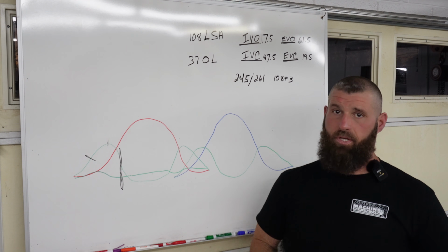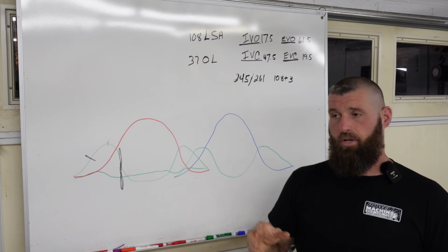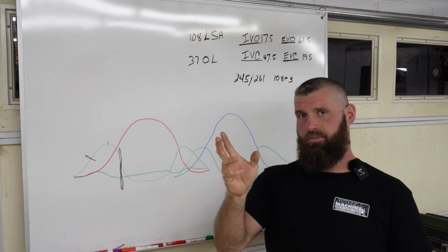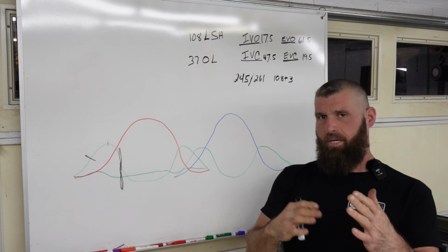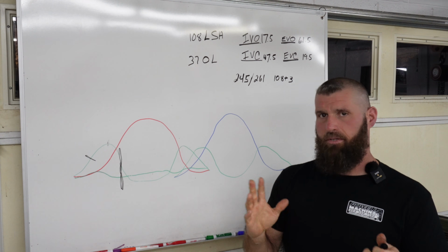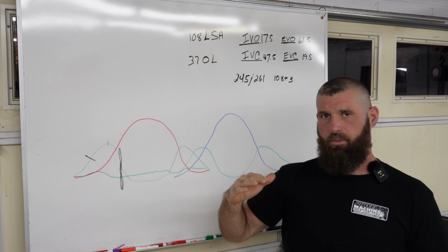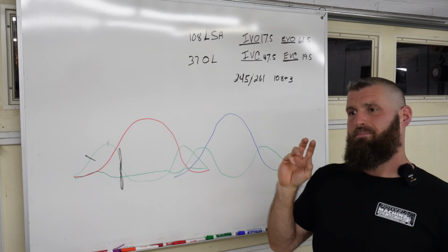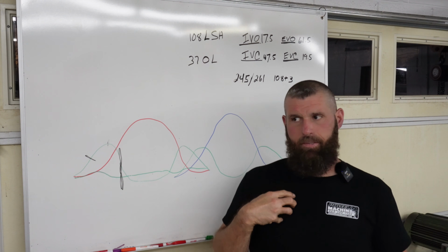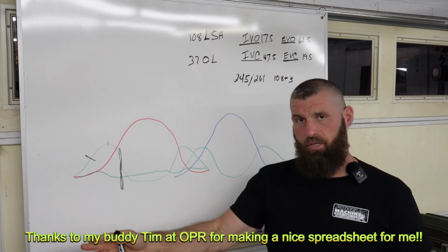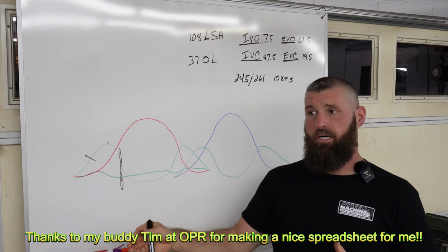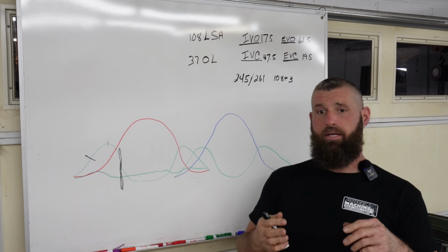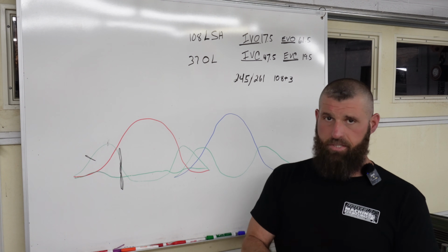So how do you figure out everything else? We looked at the exhaust flow, and there is some validation to 80% and 70% and all that. We got a little sliding scale spreadsheet that says if the percentage is here, then we'll put this much split. If the percentage is here, this much split. But more than that, I find it depends on whether it's going to have a full exhaust, or mufflers, or just open headers, plus the header size, plus the exhaust port flow.